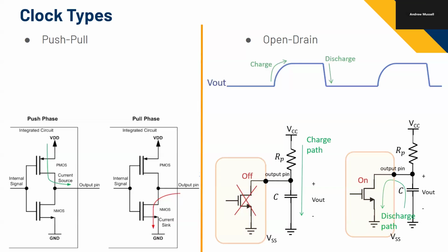Yeah, Alex. The microcontroller has a bunch of ADC pins, but then it has only 2 DAC pins. Why is that? You want ADCs, analog to digital, because that's usually how you're sensing analog signals. If I wanted to sense an analog signal, which is probably what you're doing more often, you would connect that pin to the analog signal, like the accelerometer sensor.